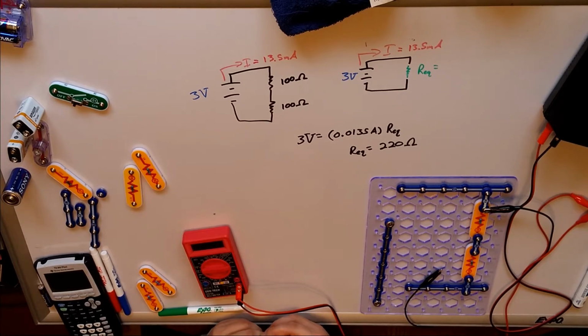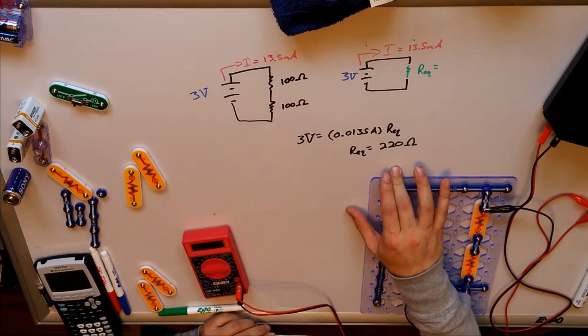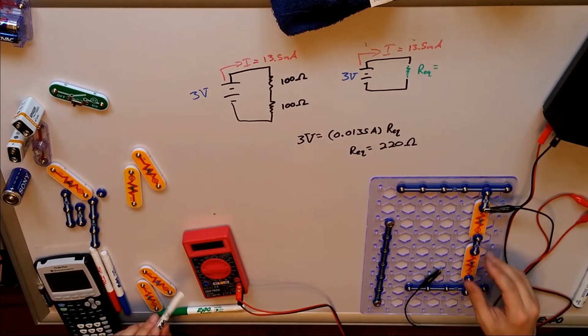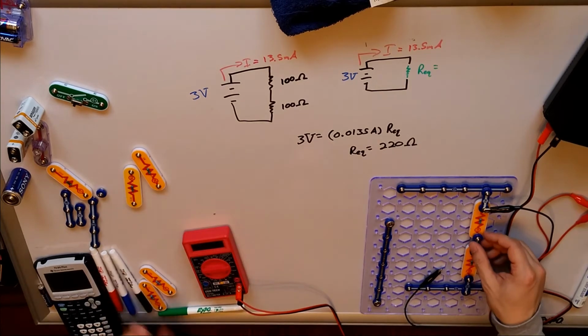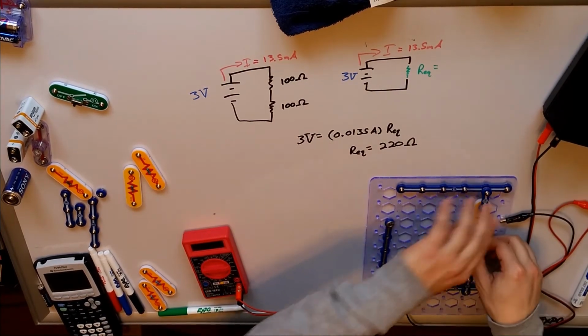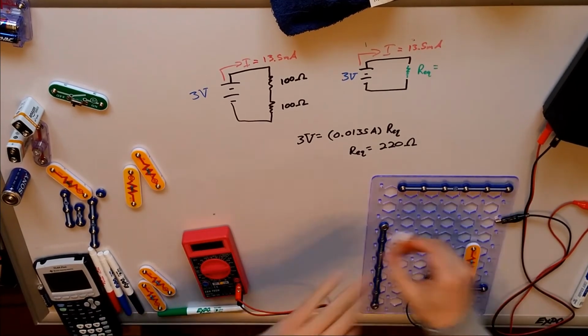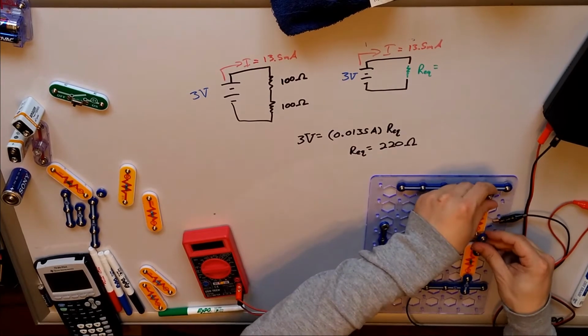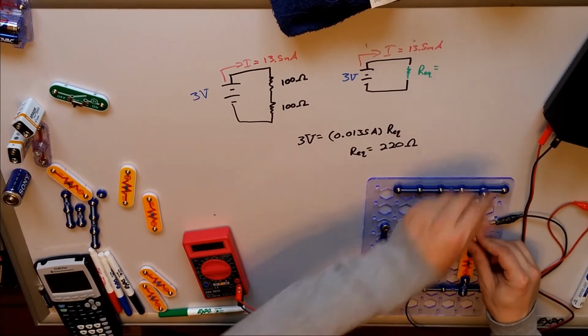Well, it's a little over 200. We've got some fluctuations here, of course. A little over 200, that means that, I've got 2 resistors. Maybe it just multiplied it by 2. 2 times 100 would get me about 200. Okay, let's try that out. Let's swap one of these out from a 100 to a 1000 ohm, and we'll see what it does.